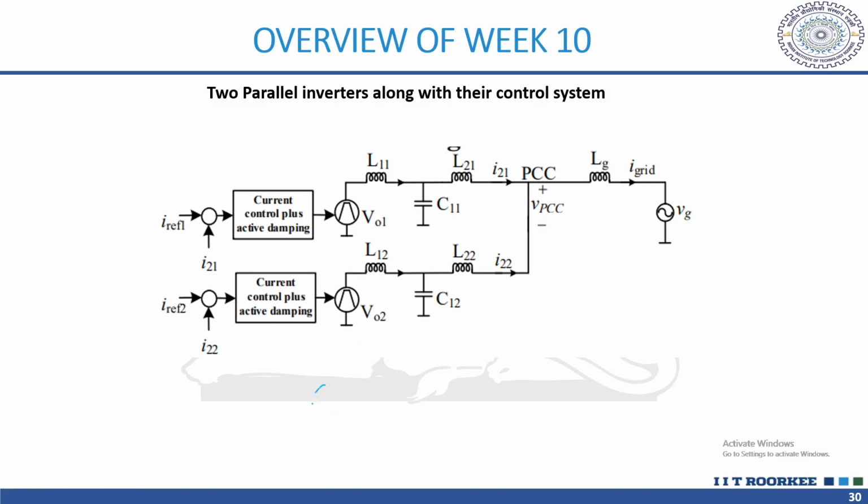And these G matrices are calculated using the superposition theorem that we all know: when we have multiple sources, we can activate one source at a time, observe, and then add their effects, as if the sources were activated at the same time instant. For voltage sources, we short circuit them; for current sources, we open circuit them.